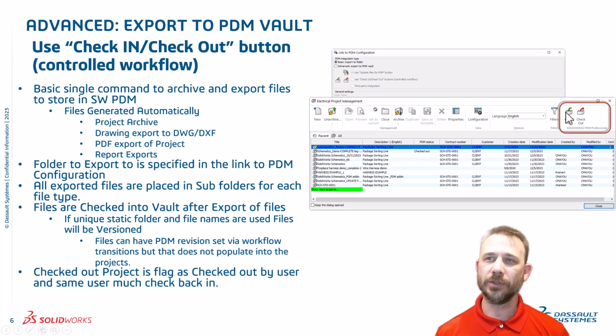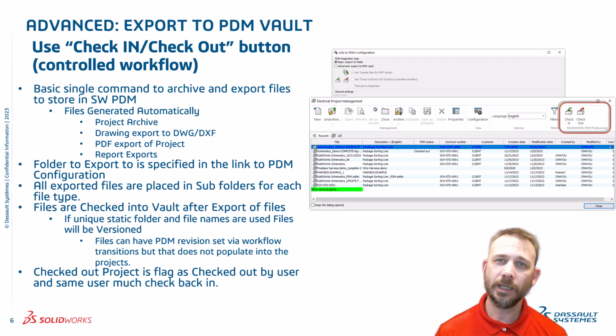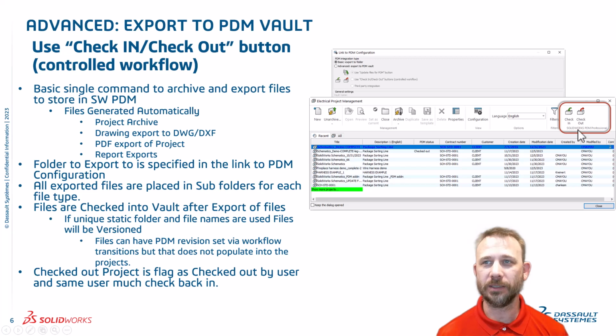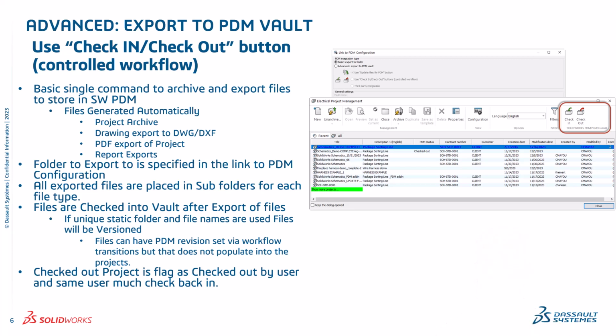So one thing when you're using the check-in, check-out functionality, whoever checked out that file or that project must check that file back or that project back in, right? So that's a typical PDM workflow. So be cautious if you are using the check-in, check-out functionality and you're using a client-server install with everyone using the same SQL server and everyone using the same application data folder, you will have to make sure that whoever checked it out is going to check it back in.